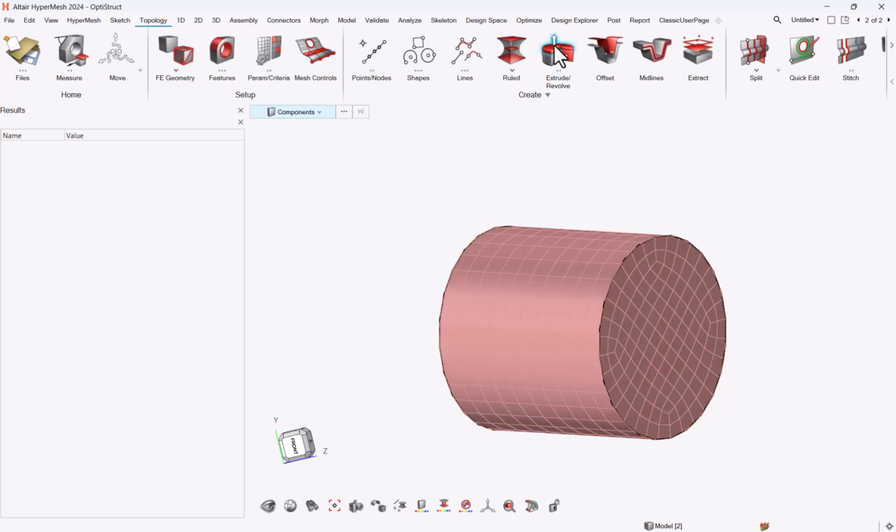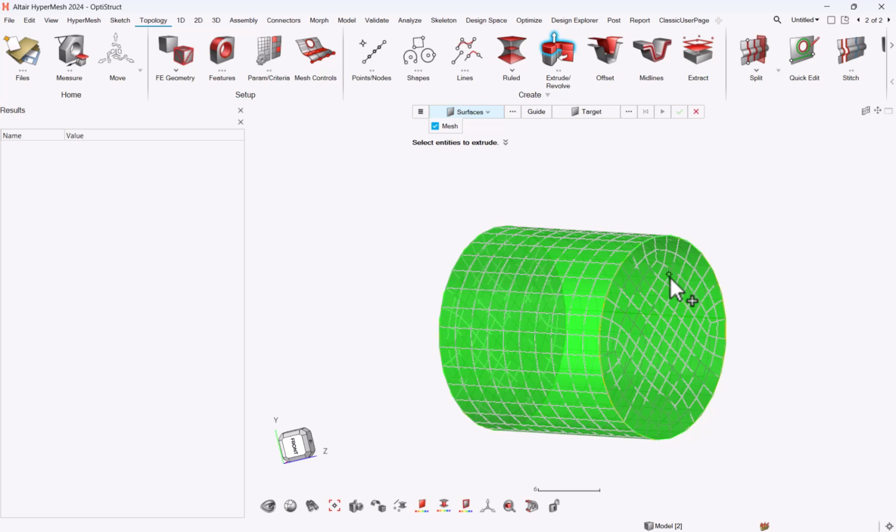As I got the request once, if you have a solid mesh, so here on this face, I just have a solid mesh, you can also select facets directly. So here I can take this facet and again extrude it by 20 millimeters.